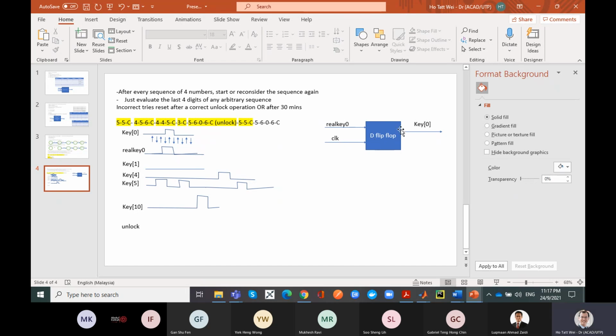Okay, so this is a way for you to actually keep yourself sane, that you can only expect the inputs to change on every clock edge. So this can change whenever, but this will update at the nearest clock edge after these changes. You follow me?